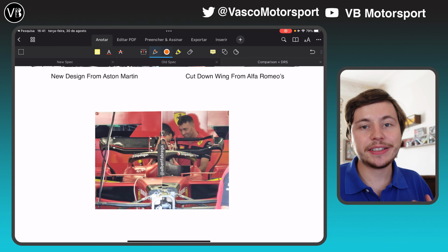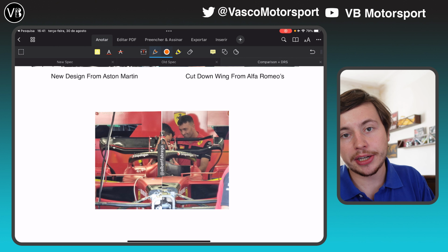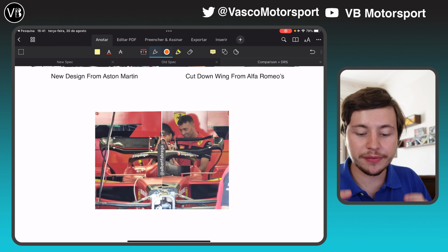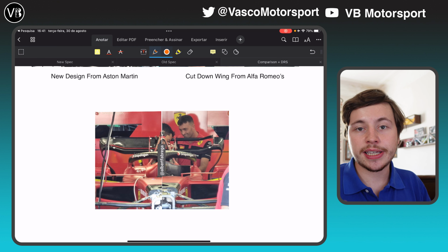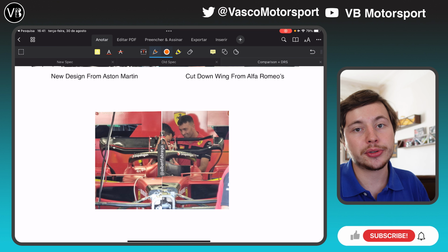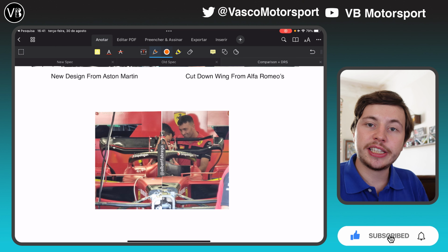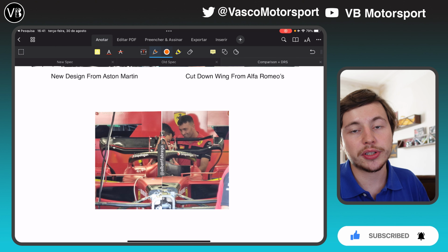And in order to win at Monza, you need good traction, so you still need a rear wing that, even though it has low drag, produces enough downforce to glue those rear tires to the ground, so you can put your pedal on the accelerator and go fast around the straight. So that's the very interesting trade-off that teams are trying to find between cost and speed for circuits such as Spa or Monza, and hopefully you now know all about it.